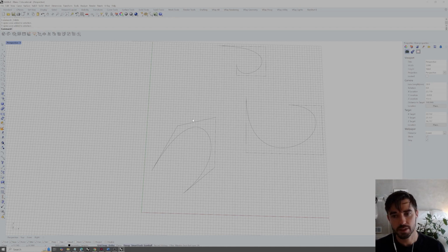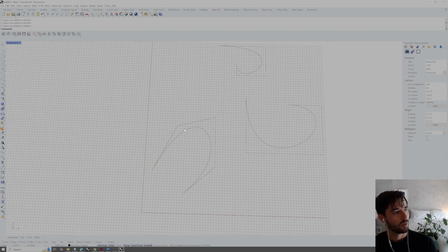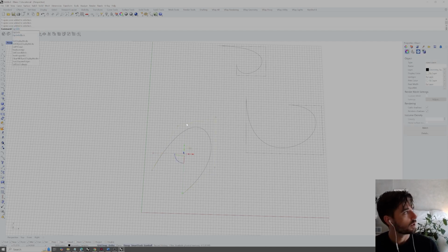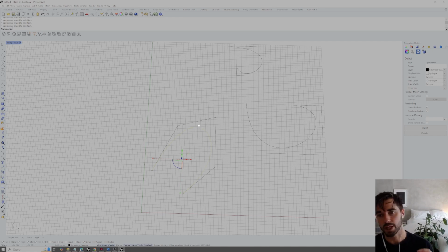So the basic idea here is that to construct a NURBS curve, we actually need to first explode the polyline. So now we have each of the line segments, and then whatever the degree of the curve is, which by default is degree 3, is the number of iterations of division connections that we are going to need.